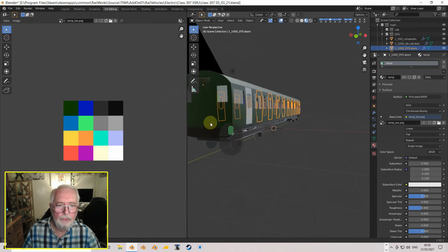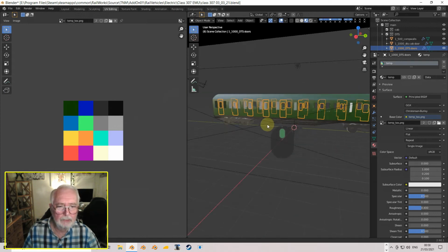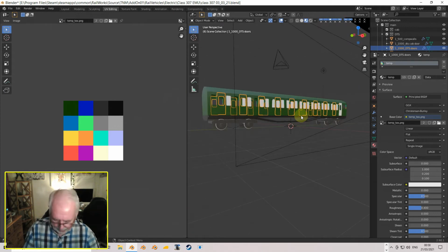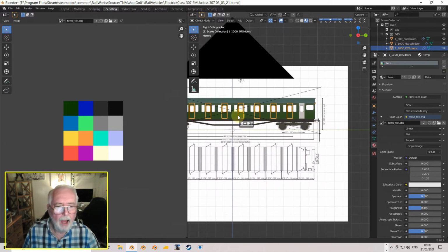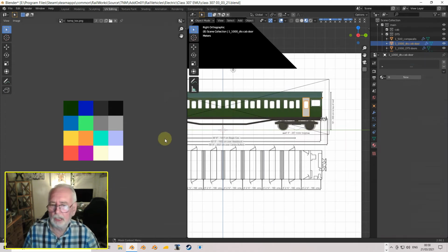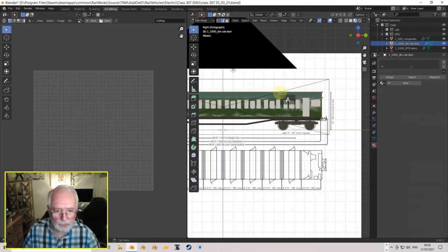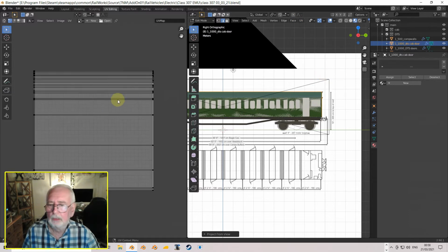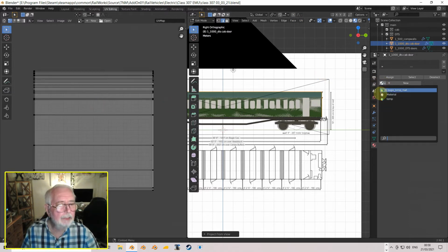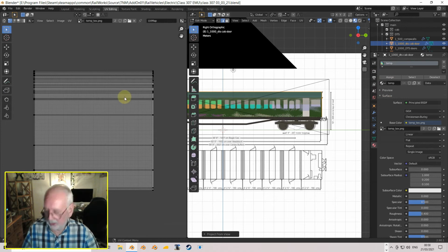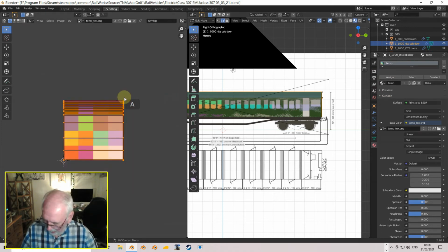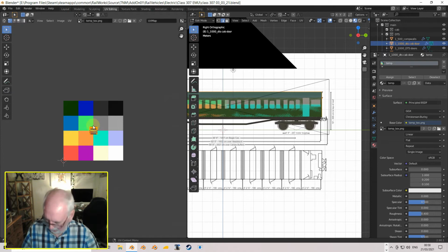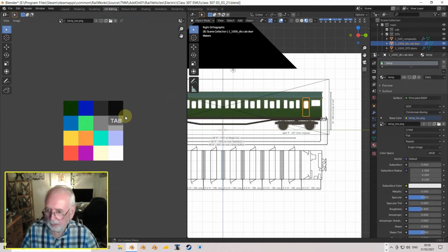And now the doors have got that same green texture. So again, side on, and we want to do this door. So again, edit mode and select all with our A and project from view bounds. Okay, again, make sure the temp material is assigned, select all, scale, grab, and there we have it.